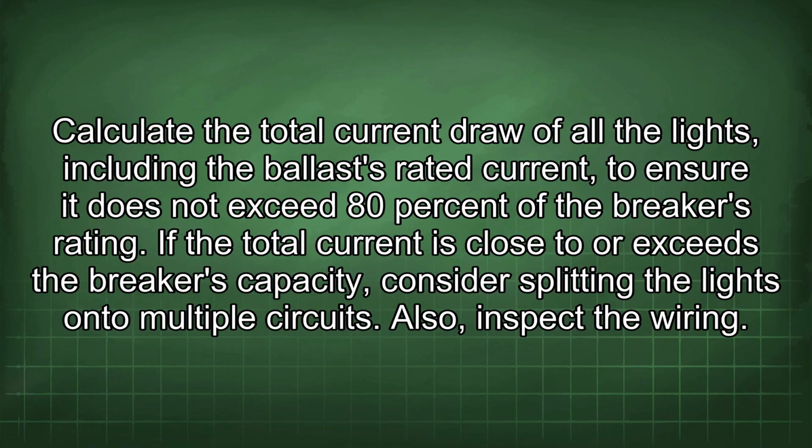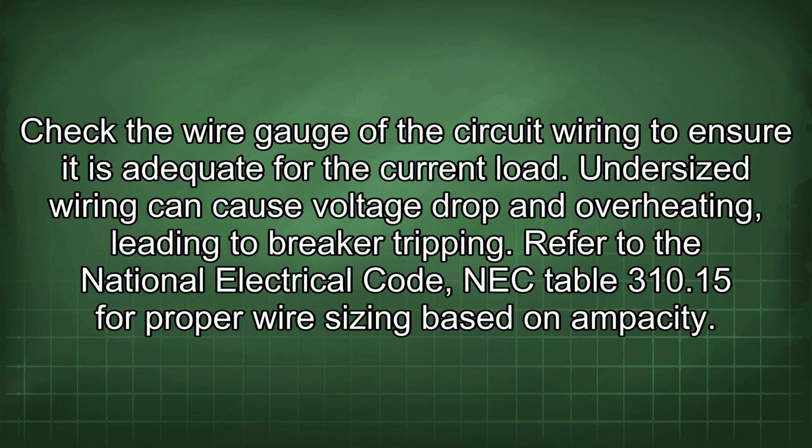Also, inspect the wiring. Check the wire gauge of the circuit wiring to ensure it is adequate for the current load. Undersized wiring can cause voltage drop and overheating, leading to breaker tripping. Refer to the National Electrical Code, NEC Table 310.15 for proper wire sizing based on ampacity.